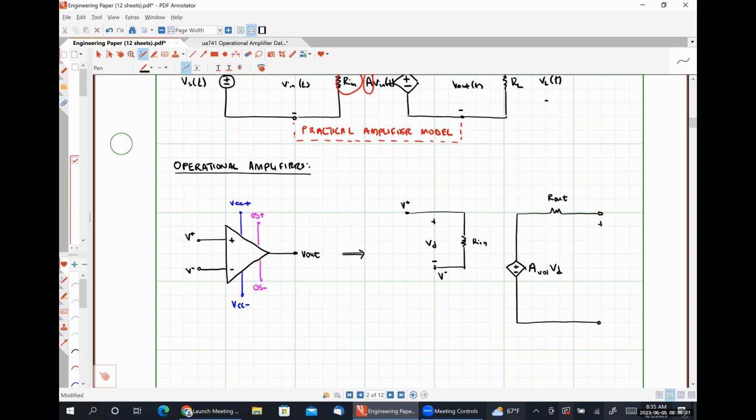These are our output terminals, V out, and we always choose to have the negative polarity terminal of our output voltage set at ground. So this serves as the reference for our circuit, and I am going to go ahead and extend this ground rail out to the left as well, so that it serves as the reference for our non-inverting and inverting input voltages.